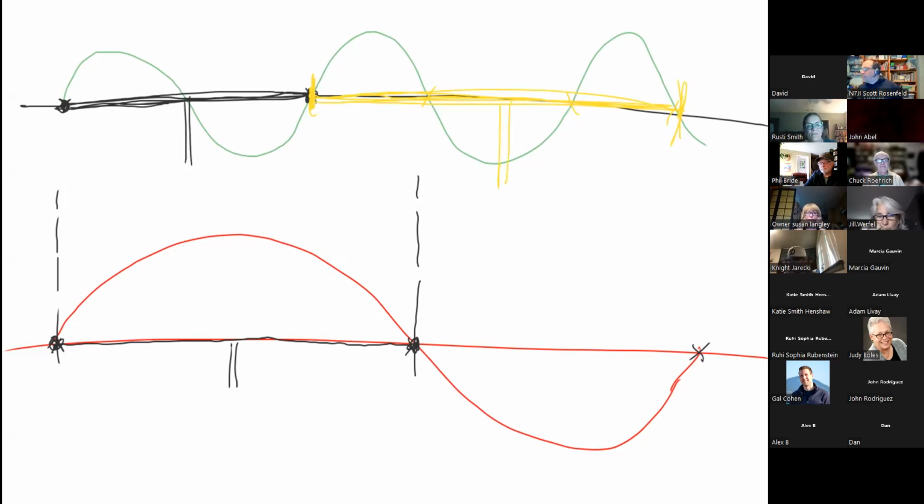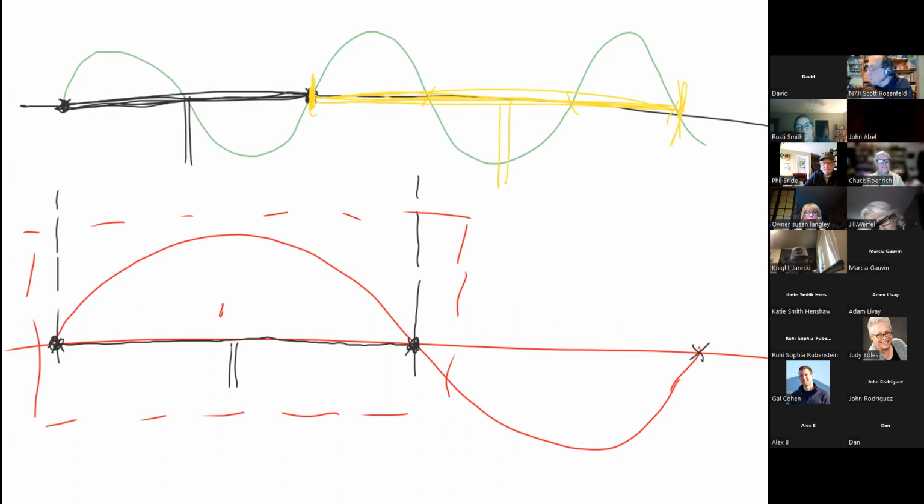So now, what's important to note here is we're dealing with a couple of different things. This is the smallest antenna right here for which that happens to be true. And it happens to be a half wave, which is why a half wavelength dipole antenna is the simplest antenna. It's kind of the fundamental building block. So if that's a half wave antenna, how about this one up here? What would you call that? Full wave. You'd call that a full wave or a one wave antenna, a one wave dipole.